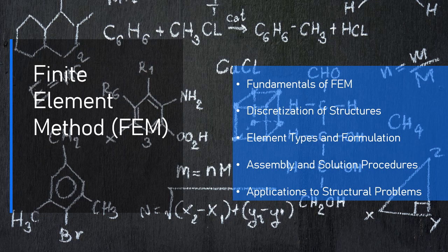It is easy to generate and computationally efficient but works best with simple geometries, like rectangles or squares in 2D, and cuboids in 3D. Advantages: fast to generate, efficient for regular geometries. Disadvantages: limited flexibility for complex shapes.